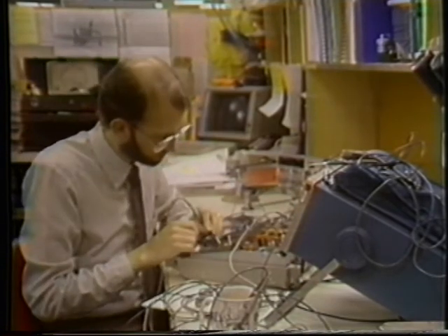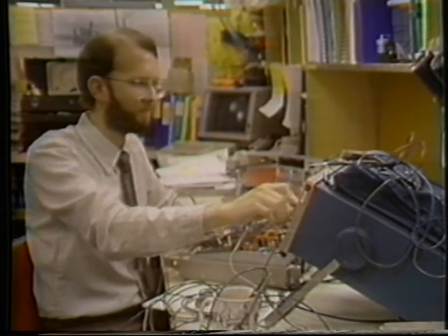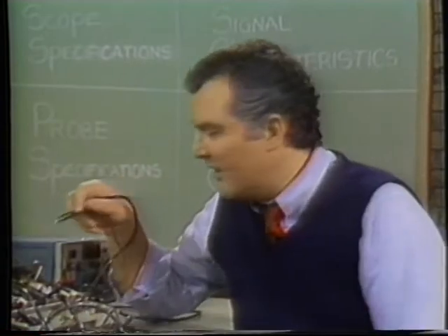The high Z probe, yes, that offers higher resistance, but its high capacitance will excessively load the circuit and limit its bandwidth. And even if you could accept that, both probes attenuate the already low voltage signal, degrading the sensitivity of your measurement. Impossible? For a passive probe, yes. But you could try an active probe.